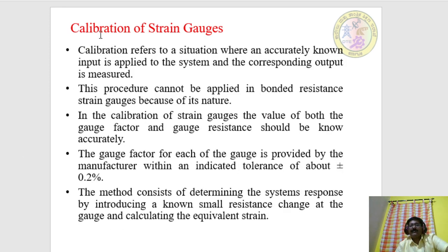Now we'll see how exactly the calibration is performed for strain gauges. You are well aware that calibration refers to a procedure made to operate strain gauges accurately, with a known input corresponding to the output which has been measured.